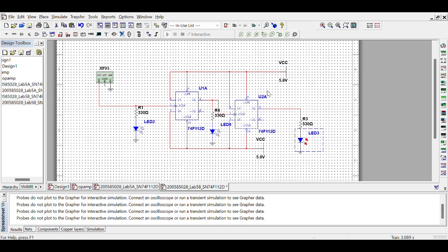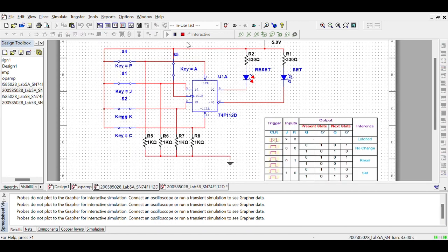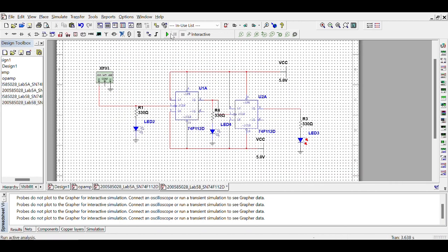So if we go and run this now, just make sure this guy's stopped. So we'll go and run this, and you can see, like I mentioned, the first LED is going extremely fast. It looks like it's almost consistently high. This one, you can clearly see there's a solid on and off flash, and then this one you see a very delayed flash. And so that's exactly how we can chain JK flip-flops together and create this system where it slows things down quite a bit.